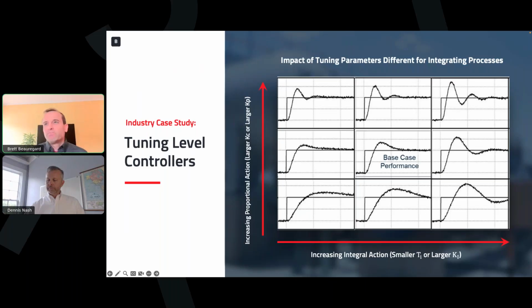I've shown this slide dozens, if not hundreds of times in classes, and with pretty much regularity, you'll get a forehead smack because people have spent weeks trying to get rid of this overshoot, and it's just not possible. Okay, so that's one of the traps you could fall into with manual tuning, is that you'll never know if you're done. You'll never know if you quite get to that best case that you want, because with tuning an integrating level style control, you're really just trying to find the best spot in a bad situation.